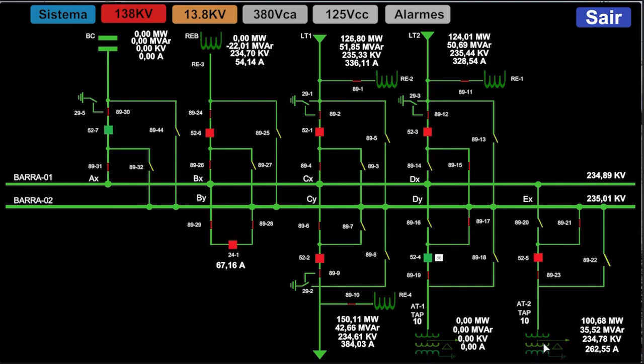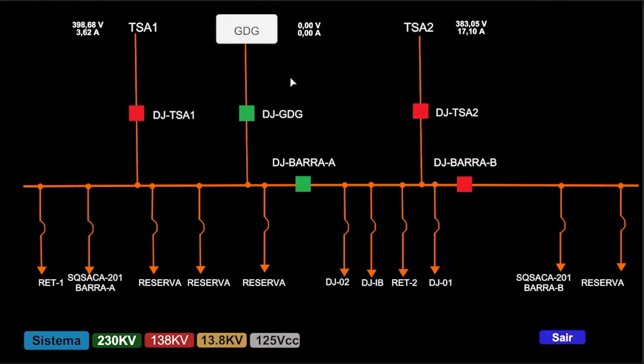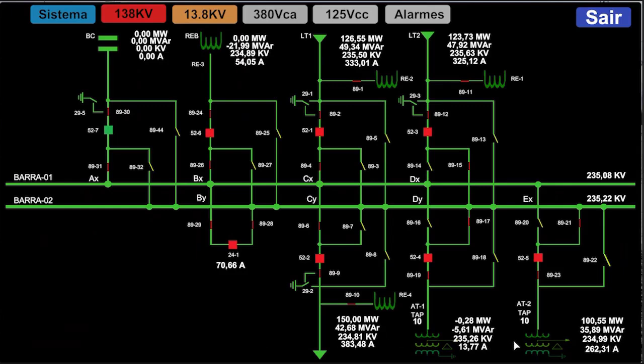Here, all my load is coming through this transformer. I'm going to unlock my 86 and close this circuit breaker. And the load is recalculated. It drew 13 amperes, probably because of the auxiliary service configuration. Here, transformer 2 was left with the essential loads, while transformer 1 was left with the non-essential loads, and that is the reason why the load is relatively low on the transformer in this scenario. And then there's tap changing, all of that affects it.